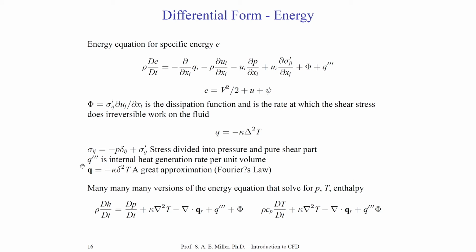The form of the energy equation is more varied than the momentum equation and conservation of mass equation in CFD theory and practice. There are many different types of the energy equation. Instead of the specific energy, we might have an energy equation written for pressure or temperature or entropy. And depending on the application, use of different energy equations might give some advantage or particular disadvantage.